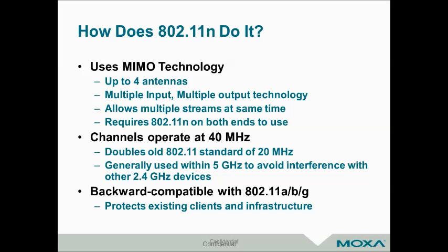So most manufacturers have chosen to implement either a 2x2 or a 3x3 MIMO system, and that gives a good sweet spot between having enough antennas for a good MIMO system and good bandwidth, but not so many that it makes engineering the product difficult in terms of the polarity of the antennas.